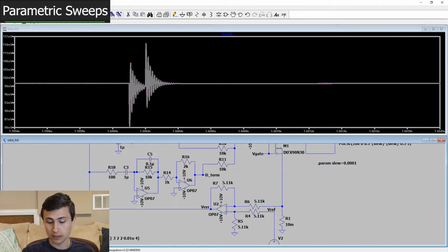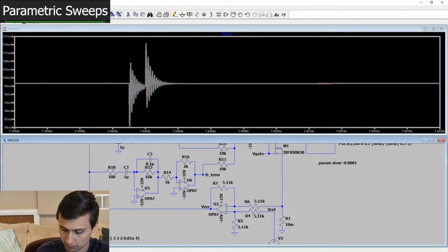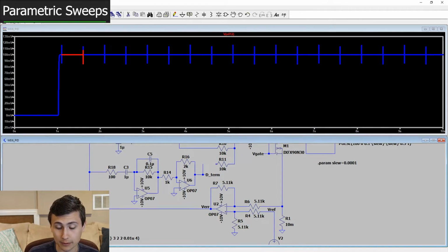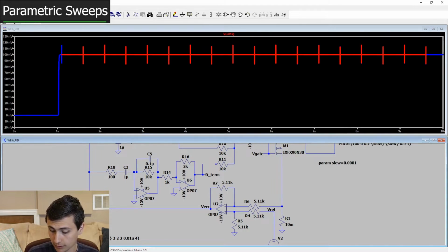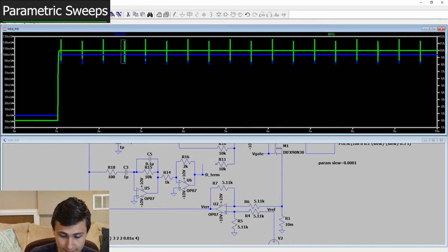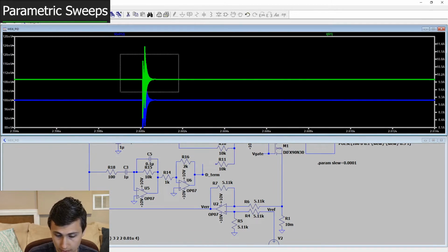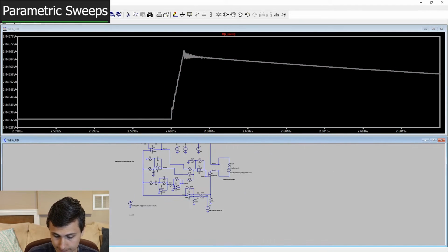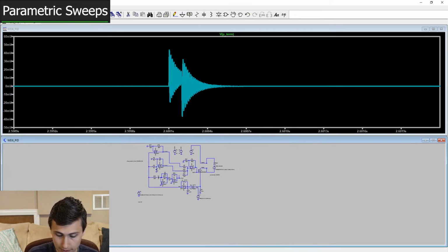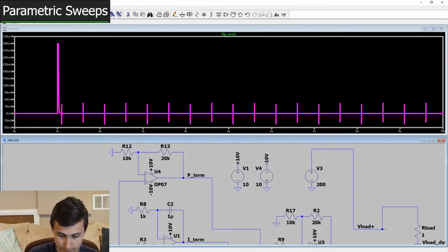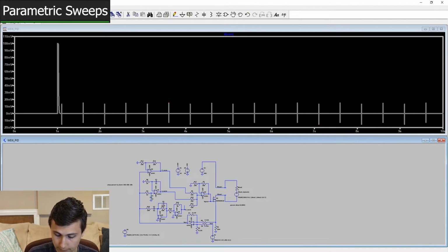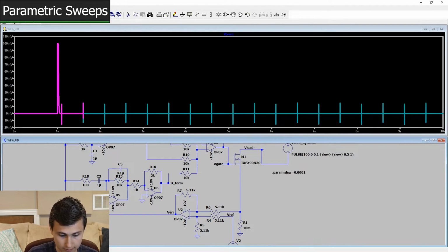Okay, just a sanity check. Let's remove our D term from the equation. Let's just cut that trace. Let's rerun the simulation. Let's look to see how the controller responds. Let's see if it was really coming from the D term, or if I was just blaming it for something that was not its fault. Looks like there's still a little bit of that nonsense. Looks like it's coming from our P term. All right, I'm convinced.